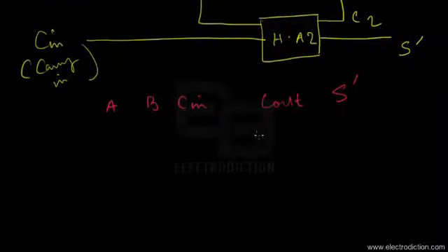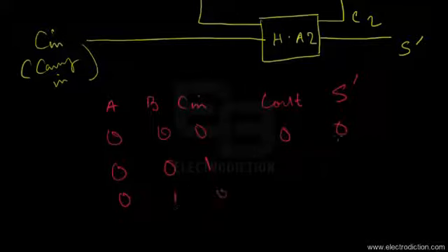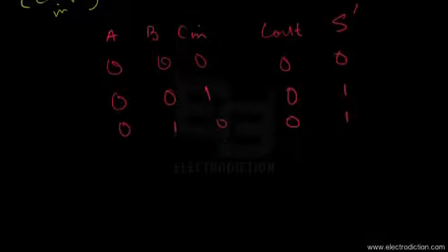So for certain types of input combinations in which all the bits are zeros, the sum and carry are both 0. For certain input combinations where any one of the bits is just 1, for this case as well as certain other cases like this, the sum comes to 1 while the carry bit is 0, as there is no carry at all.